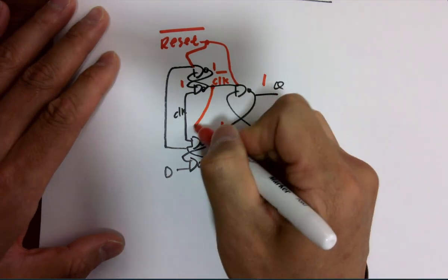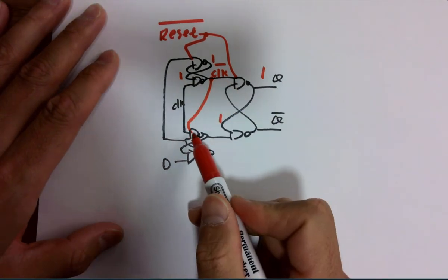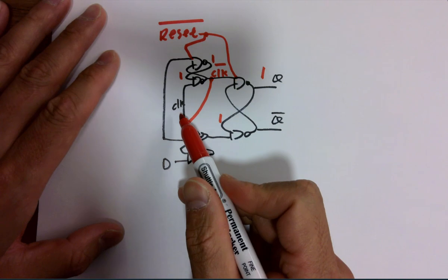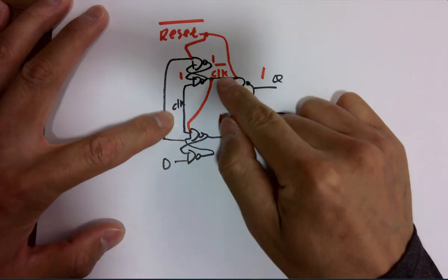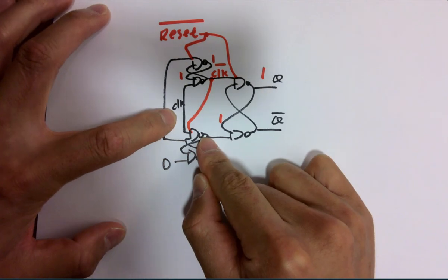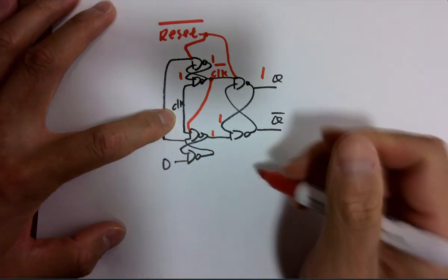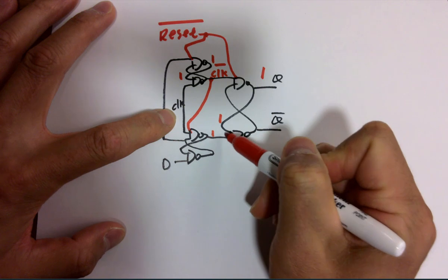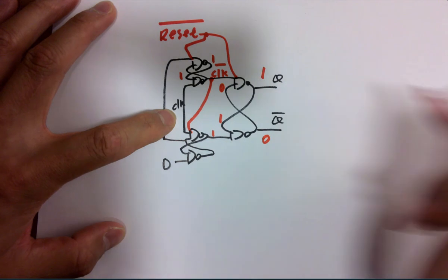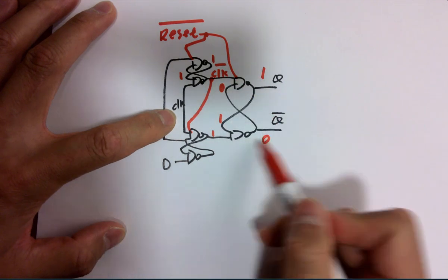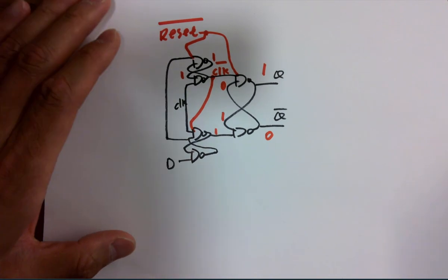And remember this line, okay? Don't forget this line, okay? So clock not is being sent to another input of the NAND gate. So clock not NAND clock will definitely be 1, right? Because clock not and clock will be 0 and being inverted will be 1. So this will be 1 as well. This is 1 as well. And this was 1 here, 1, 1. Being NAND, you get a 0. 0 comes back here, 0 NAND everything is 1, so 1 comes out, 0 1 0 1, stable, okay? Eventually stable.